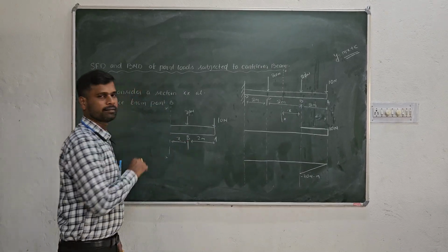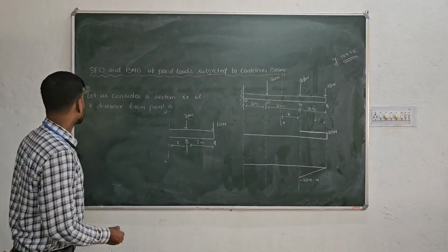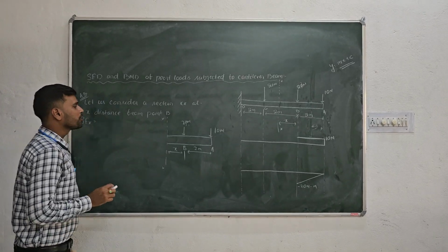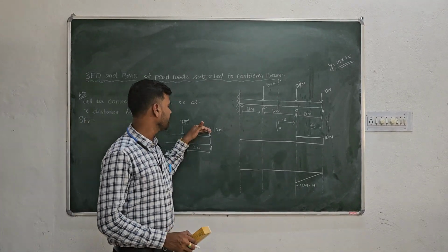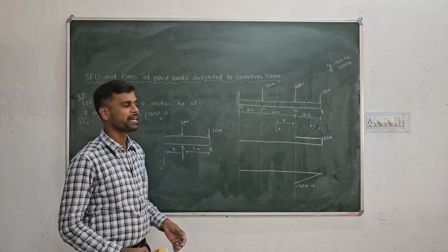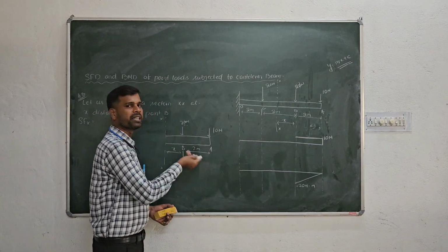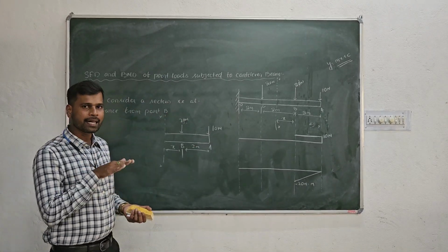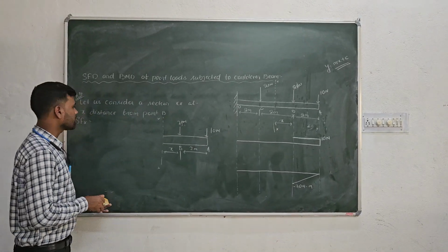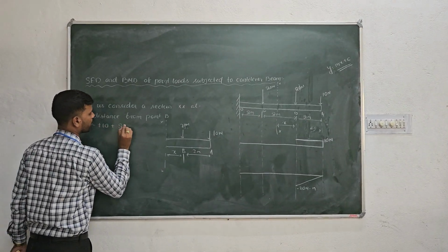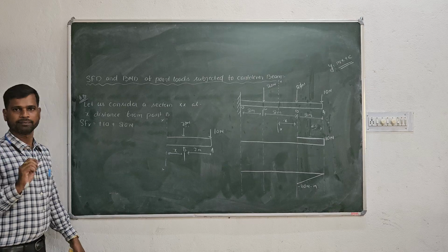So now shear force at x, how much will it be? 10 Newton, and this is making the right side of the beam go downward, so positive. Previously also we had seen. Similarly 20 Newton is also making the beam go in the downward direction. Right side going downward means this is positive, so plus 10 Newton plus 20 Newton. There is no change of sign.